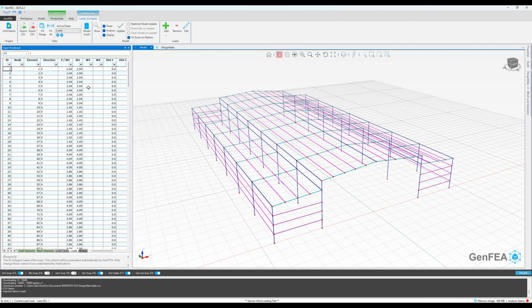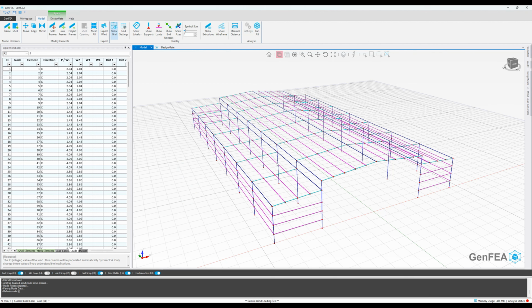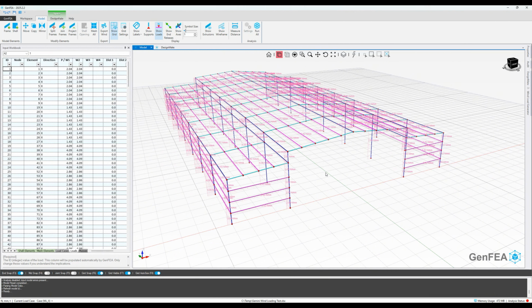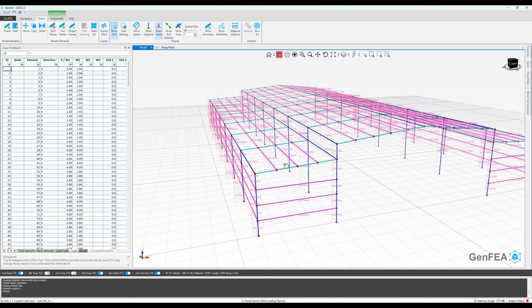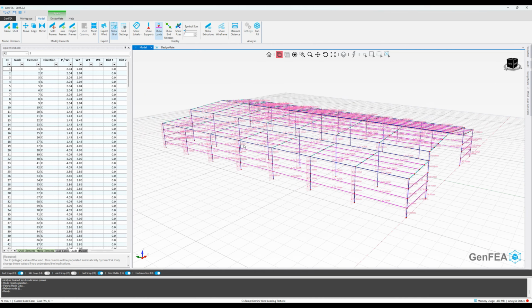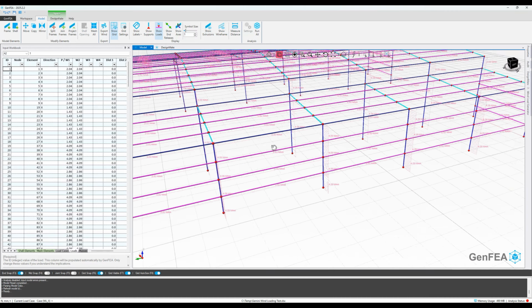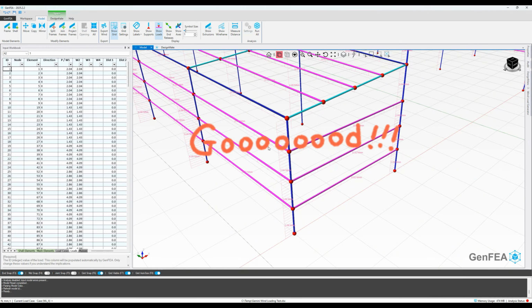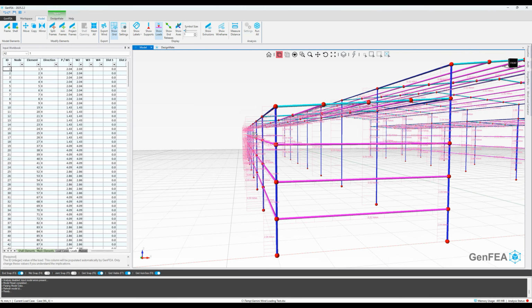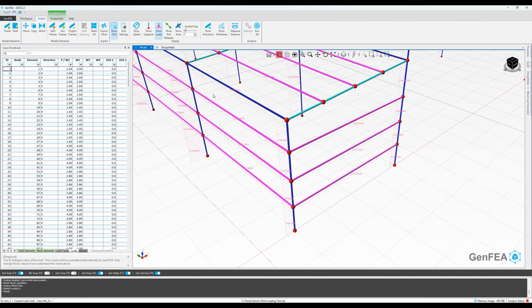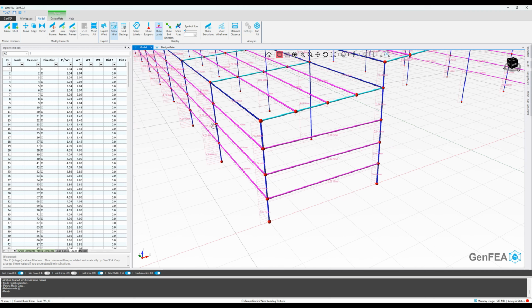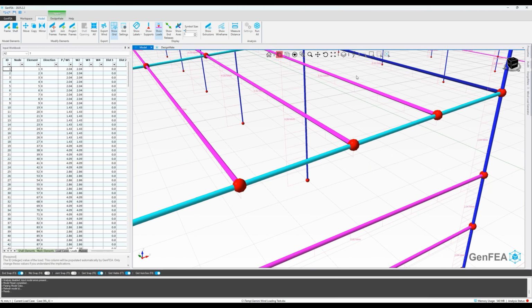But this is going to show you how quickly and how amazingly Gemini can maintain spatial awareness and understand the model from the spreadsheet input data, as well as the vision model capabilities in that snapshot that we generated. And if we switch on the wind load case here in the model and display the loads, we can actually see the loads being applied for the wind load. We can see on those external columns, more or less half of what they are on the internal columns. We can see uplift applied to all of those purlins.